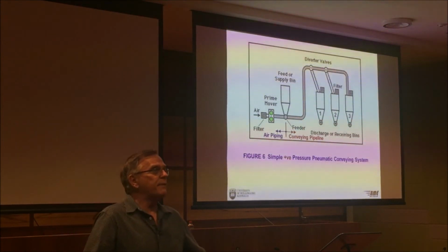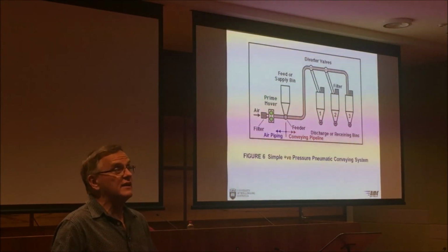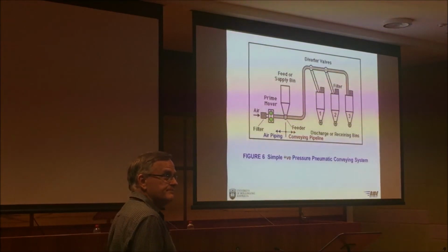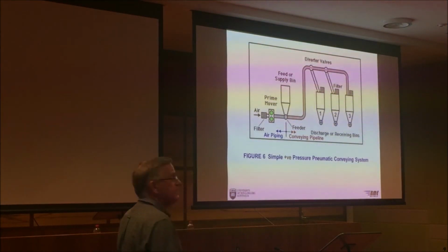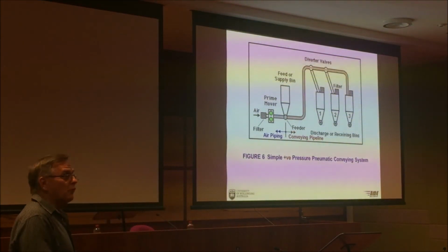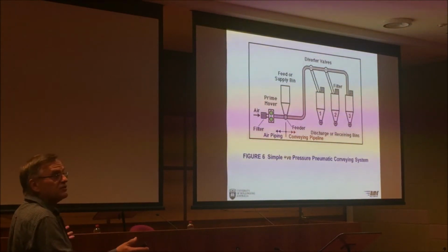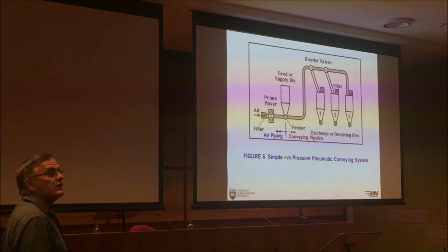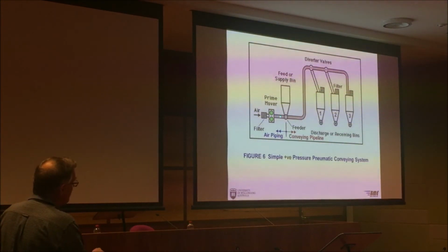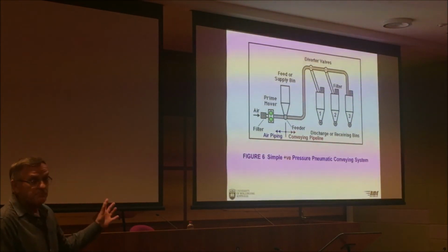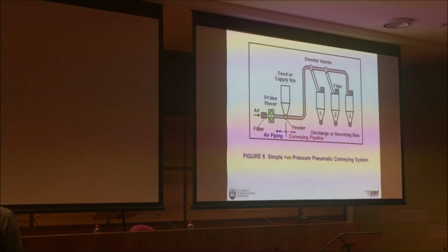And then they didn't have enough pressure available to get the tonnage they need through the conveying system. You know, it's just ridiculous that people overlook the importance of all these bits and pieces in the system. So you've got to look at the big picture. You've got to make sure all components are dealt with, including the air piping. Anyway, so sometimes it's important, sometimes it's not.